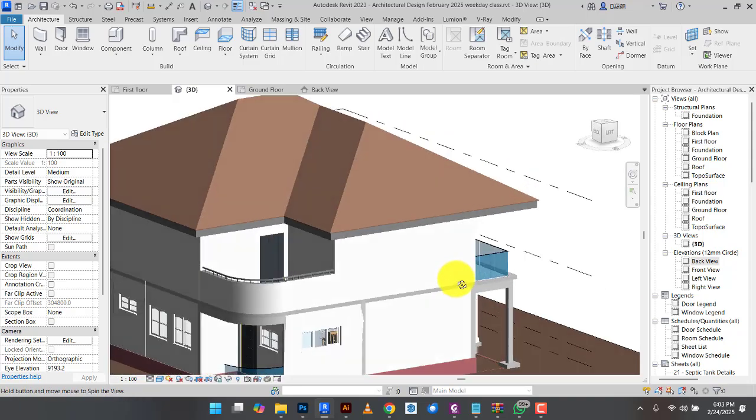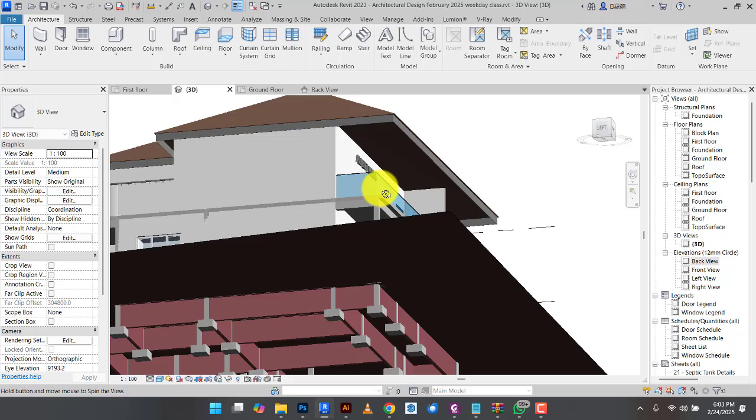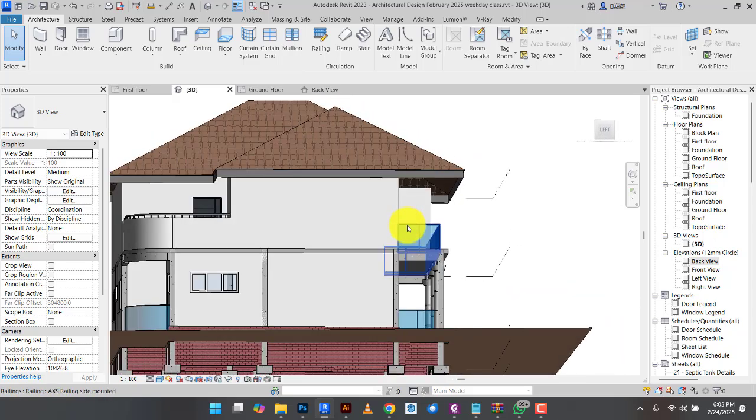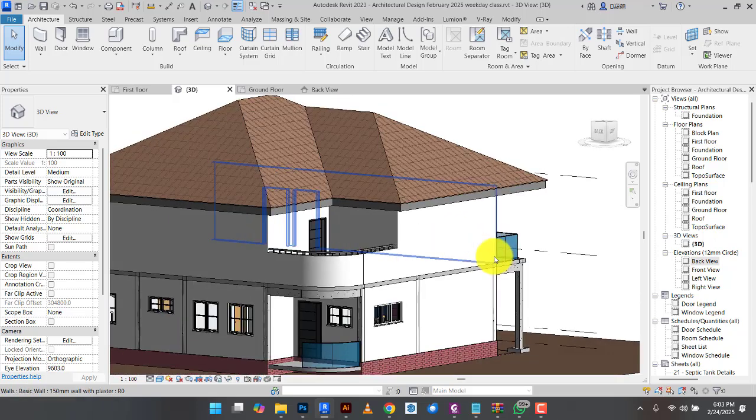Yes, let's put a ceiling. So I'll put a normal ceiling. This thing saves time. I've never thought of it this way. Normally I use the soffit. Usually the outside ceiling is different from the inside. So I do the normal ceiling inside, and I use a soffit for outside.